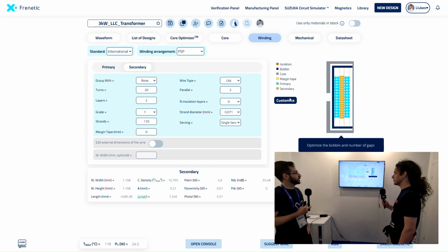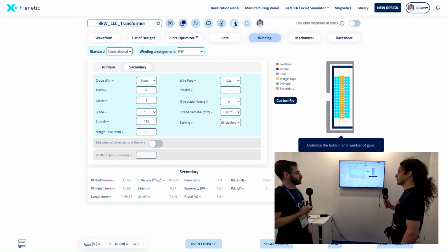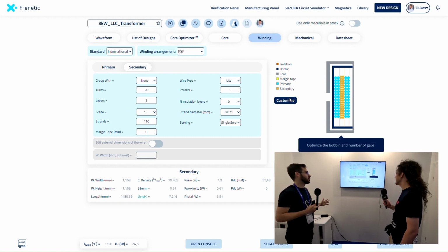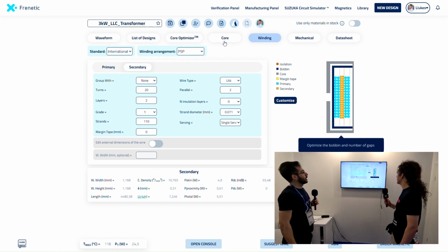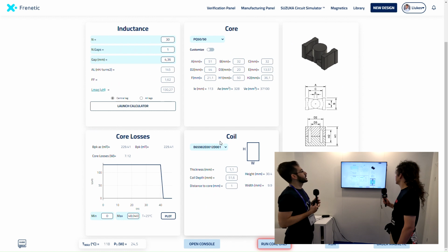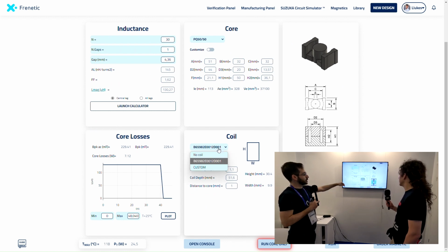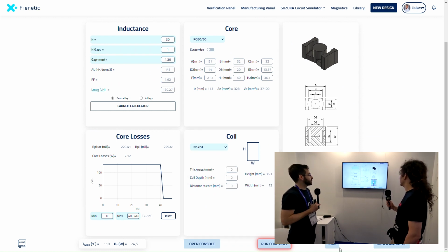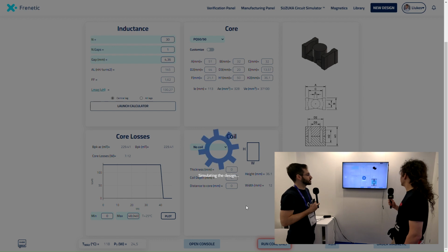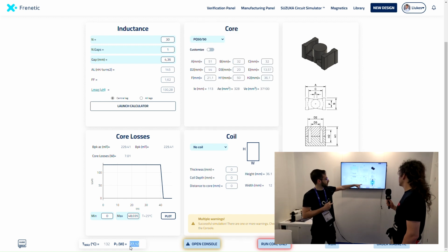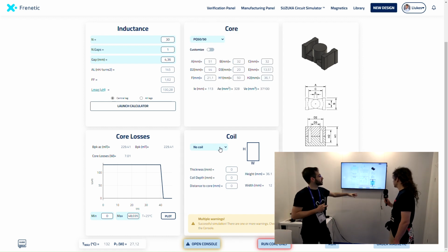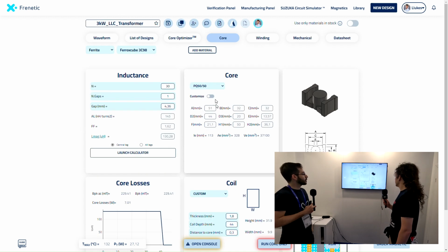So that's basically what you will ever need. As long as it's a good prediction, that's what you need. And basically, the minor things here are you can adjust the coil former as well, which can make a significant difference thermally, depending on how close you are to the gap, because you're going to have fringing effects right there.